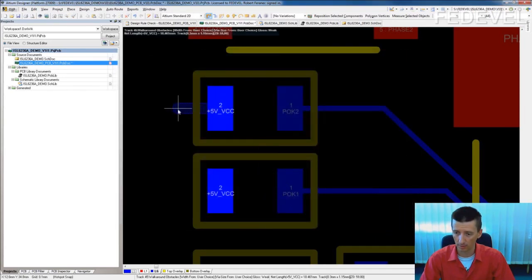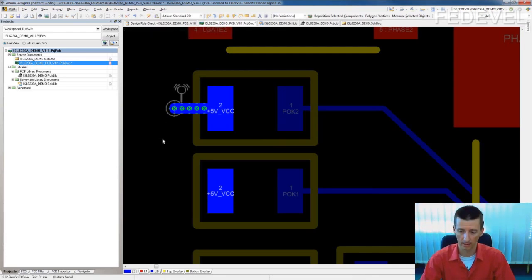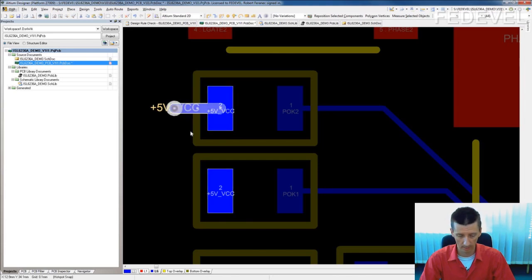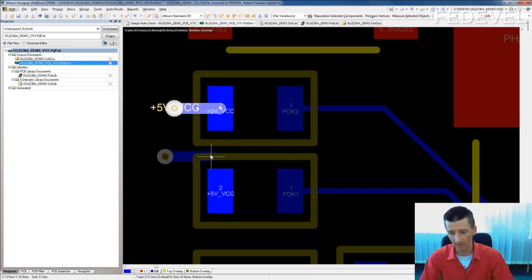Okay. Double click and then right button on your mouse. Here are the vias. Place via. And I will click here, press shift down. I will select also the via, Control C, click here. This is the position. Then when I press V, it will be snapped. See?